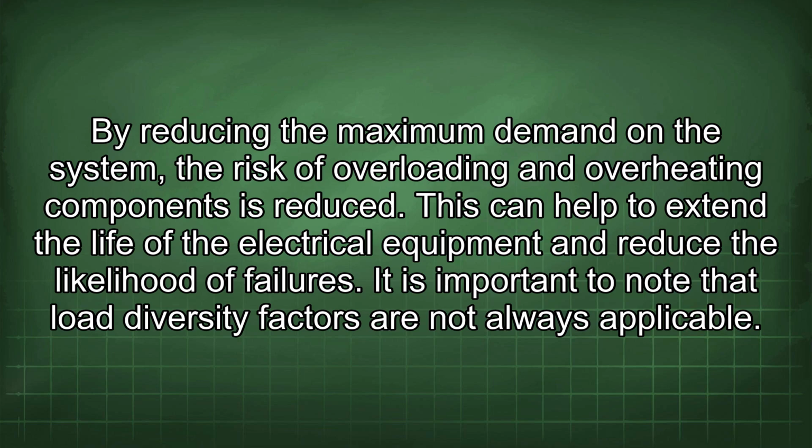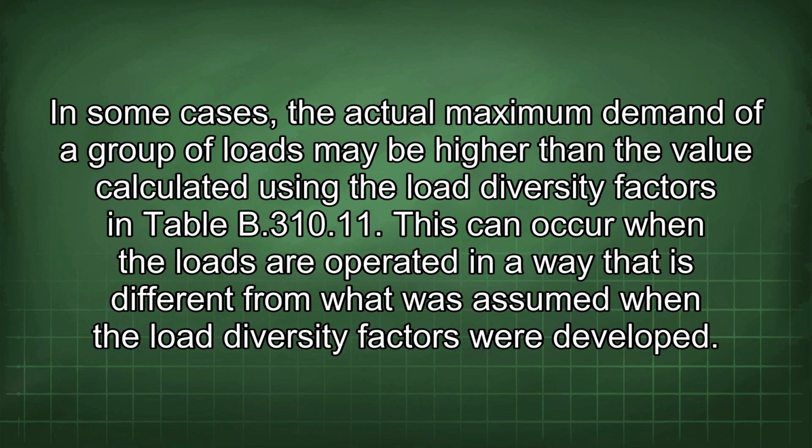This can help to extend the life of the electrical equipment and reduce the likelihood of failures. It is important to note that load diversity factors are not always applicable. In some cases, the actual maximum demand of a group of loads may be higher than the value calculated using the load diversity factors in Table B 310.11. This can occur when the loads are operated in a way that is different from what was assumed when the load diversity factors were developed.